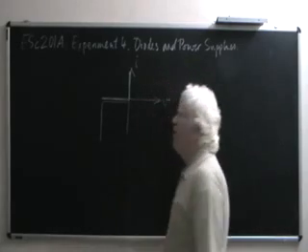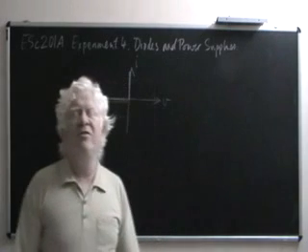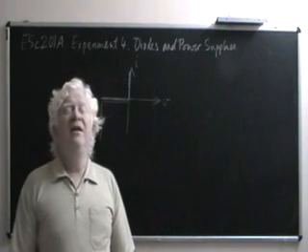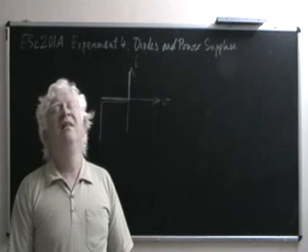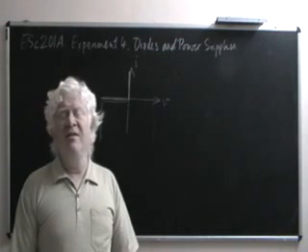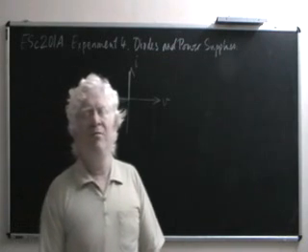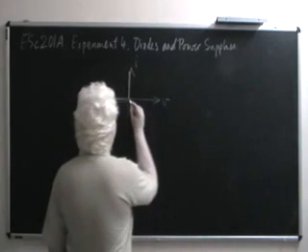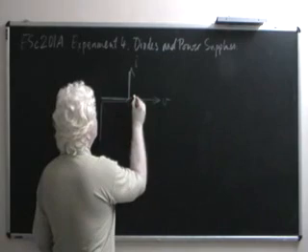Now, when a forward voltage is applied, the non-ideal or practical diode does the following. Until about half a volt is applied in the forward direction, it still hesitates to conduct a current. When voltages greater than half a volt are applied, it starts conducting wholeheartedly. So, on the positive side, the curve goes like this.